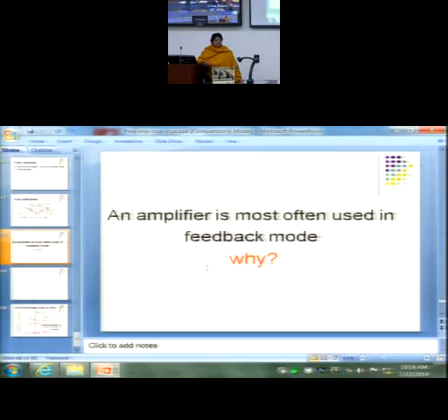So that is why we say stability. Now the circuit is stable. According to me, the circuit is stable at gain 10. This is one meaning of stability here. Negative feedback improves stability. But stability has another meaning also, which we'll discuss in terms of frequency response.